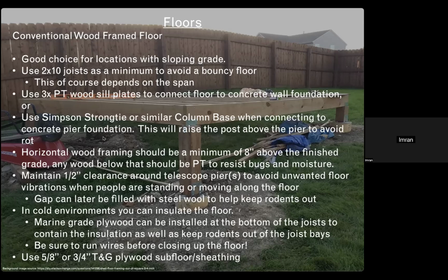Scott, just a quick question. That is mainly just to avoid rot, right? Yeah, totally. That's the only purpose for it, right? Well, it does a couple things. It not only deals with rot, but in this case it also ties the post to the foundation, which is the important thing. So your load is going directly down into the ground and dissipating.